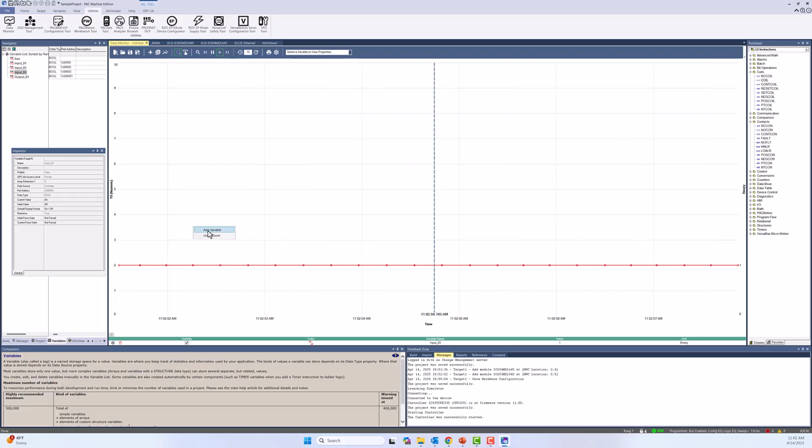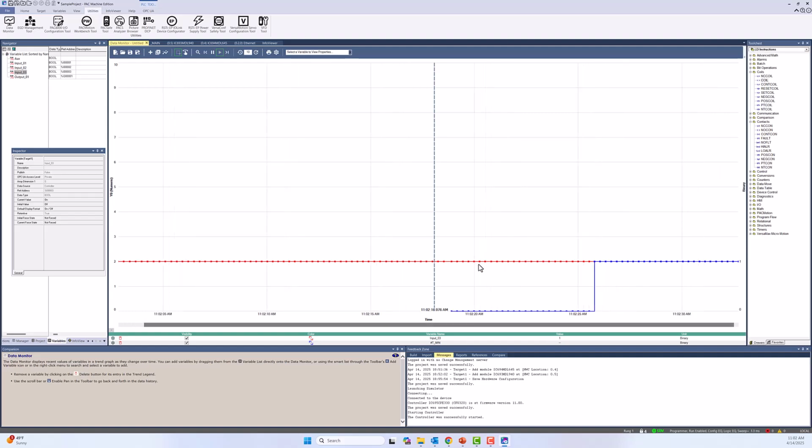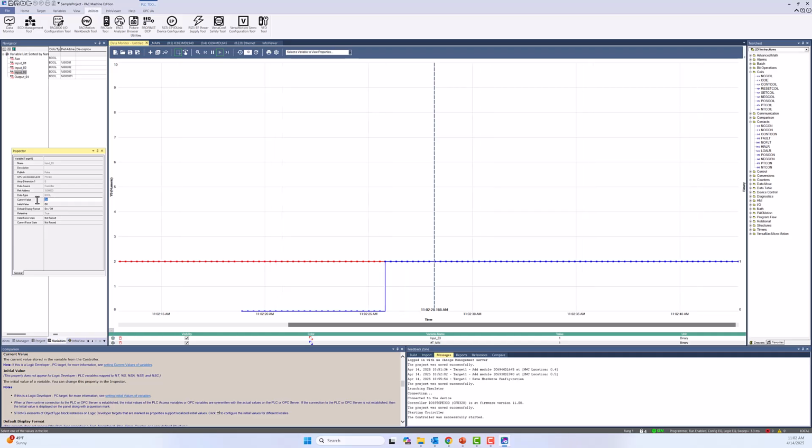So if I wanted to see, there's a bunch of pound tags, so I could add a system tag, like a pound t minutes, which is on for 1 minute and off for 1 minute. So you're going to see it transition every minute, go up high and then down low. Notice that my 1, see there's the minute, it just transitioned to a 1 and then it will go low after a minute. Notice that my input 3 is currently high. If I click on my input 3 here and turn that current value to a 0 or off, notice how that now goes low.